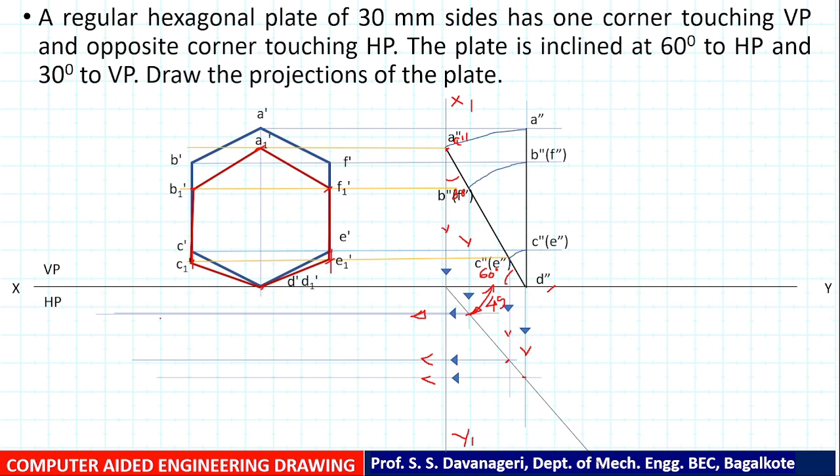After constructing all these construction lines, you drop down the construction lines from the front view. This construction line refers to points B and C. This refers to points A and D. Now this refers to points F and E. Now you just observe the intersection points.